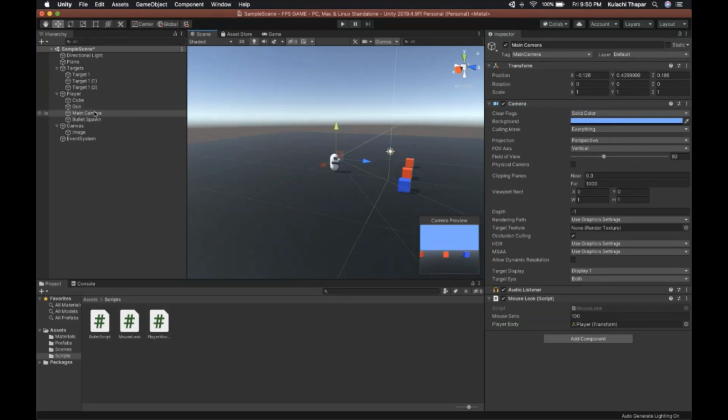More than that, if you click on your camera or any of your game objects, you can see these axes. If you look on your top right, green is Y, red is X, and blue is Z. So if you want to rotate something, you can look at these axes and tell along which axis you need to rotate. If your camera is looking 180 in the wrong direction, maybe it's your Y component that you need to change. If you change Y to 180, then it should start looking in the exact opposite direction.